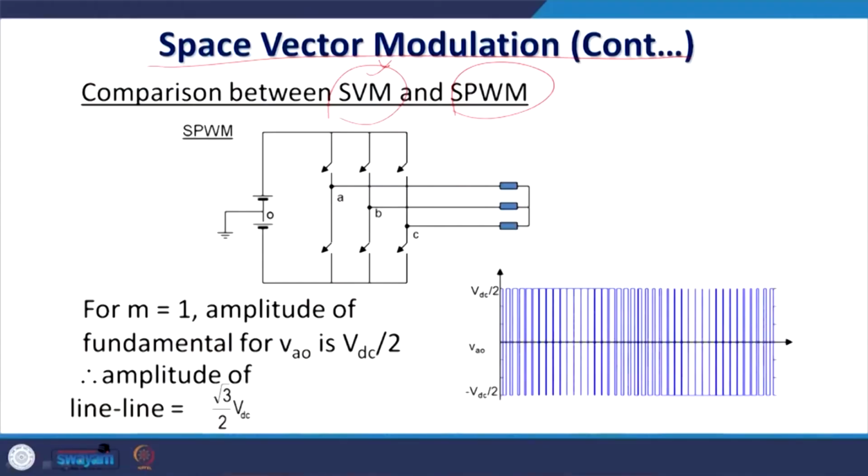SVM, but with the arrival of the digital age and fast processors, it gains over in accuracy, like exactly generating that particular THD you require, and it is attuned to vector control. So, for this reason, space vector modulation has been gaining much attention. And so, what are the other advantages?